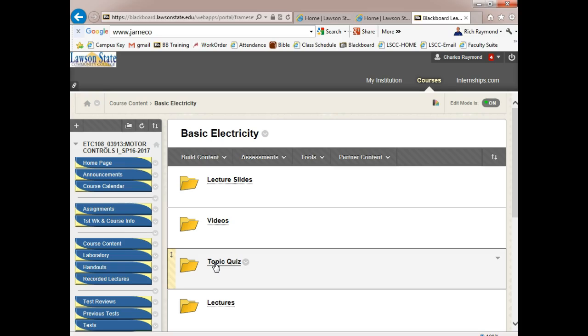We need to understand just basic AC, not in depth. So you need to know cycles. You need to know what frequency is. You need to know basically what an inductor does. It varies with frequency, right? But the big thing that we need to understand is that it creates these phase shifts, which gives us the ability to have a single phase motor. And then later on, when we get into how do we reverse a single phase motor? Well, if you don't understand phase shifts and start windings and stuff like that, it's not going to do you any good to know how to reverse a motor. And that's one of the big things we'll do.